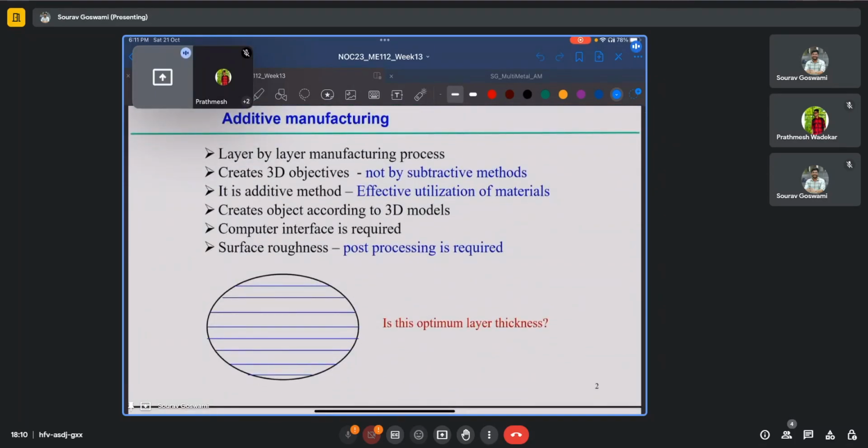First, just a very quick recap of the additive process itself. We have been talking about it for the past 3 months, but a recap never hurts. So basically, additive manufacturing is a layer by layer manufacturing process. It starts from a digital CAD model, which is first turned into an STL or an approximate model. Then it is sliced. Then the pre-processing steps also involve the calculation of the support structures. Then it is passed on to the building machine or the printing machine to be printed.